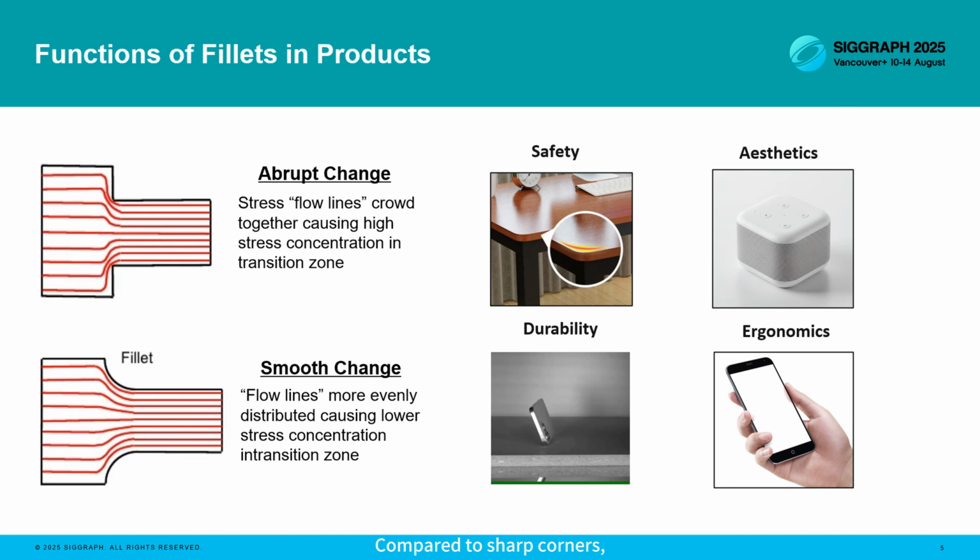Compared to sharp corners, fillets help distribute stress more evenly, reducing the chance of failure. On the right, we see how fillets enhance safety, aesthetics, durability, and ergonomics, making products not only stronger, but also more user-friendly and visually refined.